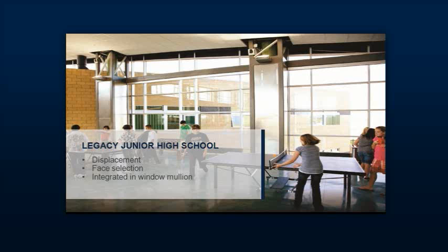Now, the other thing about it is, as I mentioned on the Jewish temple earlier, was the displacement from the sidewalls. This is displacement from floor. I am activating this floor as a thermal storage media, and it works incredibly effectively at that. Another place that used very successful underfloor displacement is the Seattle Public Library.